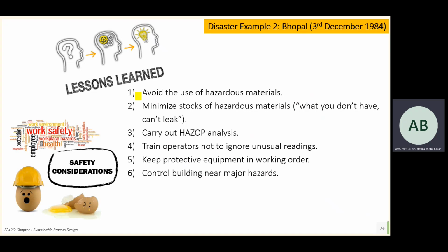Now the lesson learned over here: avoid using hazardous materials, minimize stocks of hazardous material. Okay, again, carry out the hazard analysis. Train operators not to ignore unusual reading. Okay, this one not only for the operators. Engineers should know as well. What do you understand of unusual reading?